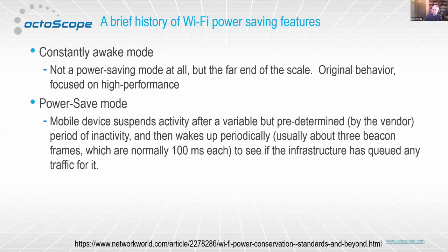Beacons in the network, for anyone who's not aware of this, are packets that are sent out on a regular basis. They give information to the devices in the network about what's going on and capabilities of other devices in the network, things like that. So they're sent out on a fairly regular basis, about every 100 milliseconds or so. So when you talk about a device waking up every beacon or every couple of beacons, you're talking about a device waking up a few times every second. So sleeping is good, and only having to wake up a few times a second is good, and it's better than being awake all the time, but it's a far cry from what you need to be able to support something like the IoT lifetimes.